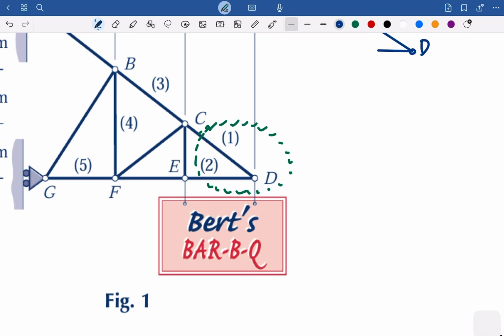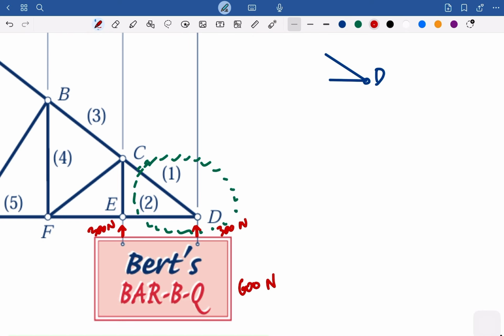or maybe before that, since this is 600 Newton, and we have two cables on the 600 Newton, each one of them is 300 Newton and 300 Newton, right? So we could just divide by 2. So the cables from the sign are 300 Newton. So on the pin D, we are getting another 300 Newton here going down, right? Okay. And then what else?